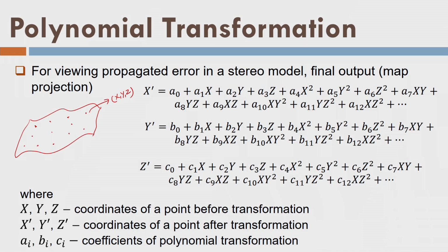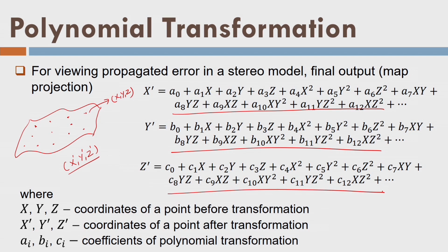After transforming those stereo models into the object coordinate system, I will get transformed coordinates as x dash, y dash, z dash, and so I am fitting a 3D polynomial through this, and these are written as these polynomials 1, 2 and 3. Once I fit these 3 polynomials for each coordinate, I can find out any new point. For example, let us say I want to find these new points here, here, here, here, which I do not know in the field, but after fitting these polynomials, I will do the interpolation and I can find out the coordinates of these 4 new points.